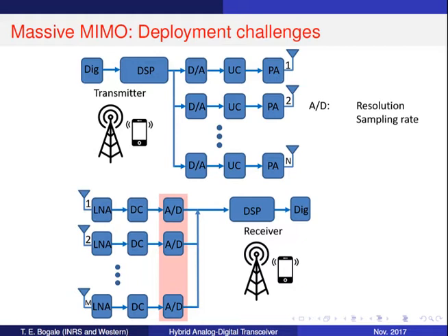The main reason for this is that in the case of a low SINR input signal, the received power at each ADC unit contains weak desired signal and strong interference signal. And to recover the desired signal by the receiver DSP unit, the resolutions of the ADC should be sufficiently large to quantize the desired signal, which is potentially weak.